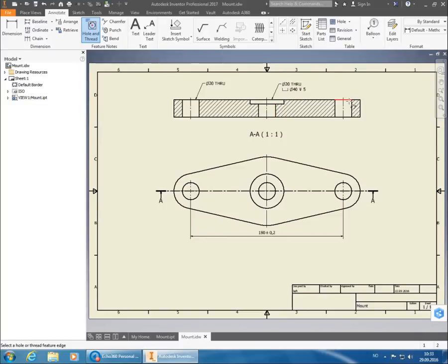Now I can either just put on a 20mm hole all the way through on this one, or I could have fixed the first one and set it to be 2 times 20. It doesn't really matter on this one. I could also use the tip behind it in order to show that it's a typical hole. In this case, I'm going to just let all 3 of them stand because I'm not going to place more dimensions on this section view except the thickness of the plate.